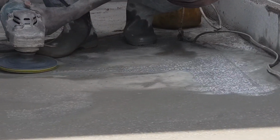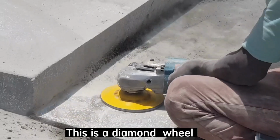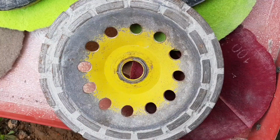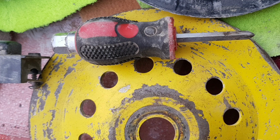We do grinding in 8 phases and we use a different pad at each phase. Let's first talk about each pad. This is a diamond wheel which is used only in the first phase. This is its front side and this is its back side. It can be removed or refixed to this angle grinder using this screwdriver.